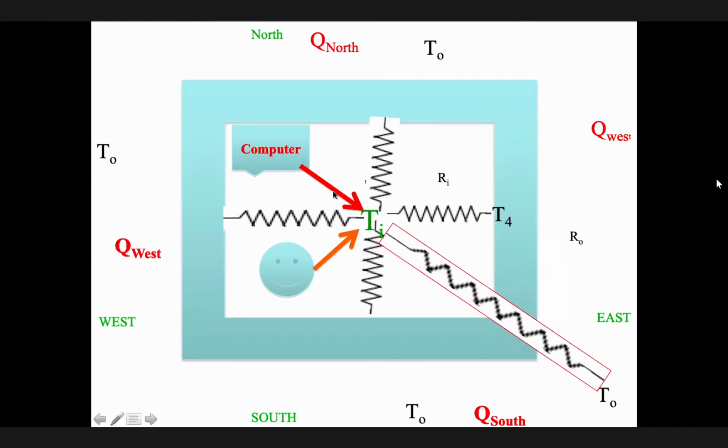The temperature inside, when I run my code, gives me something close to 0. Does it make sense, or absolutely should I? Absolutely not, because you have people inside and you have some infiltration, and so on. Therefore, the temperature has to be at minimum the outdoor temperature, but it has to be more than that. Therefore, check your equation and the coefficients that you're using, because we'll end up with, I don't know how many equations that you have.